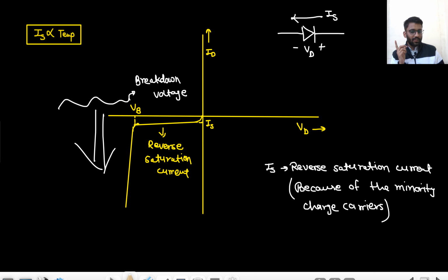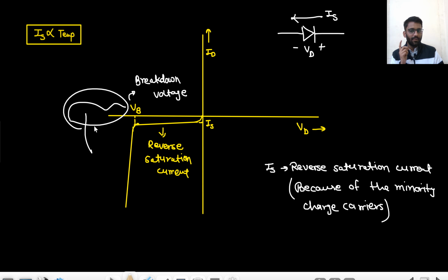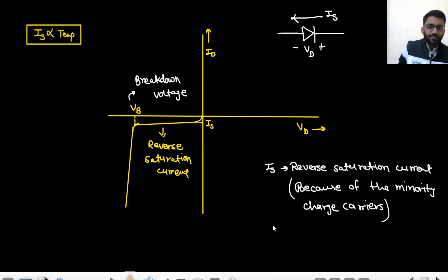The topics that we are going to study now will have no use of this region actually. But when we study the Zener diode, there will be use of this region. So I will tell you deeply about this region, why the current is increasing like this, why there is a sudden jump in the current. After that region, no matter how much you increase the voltage, there will always be a certain voltage across the diode, that will be VB. The voltage will be fixed.